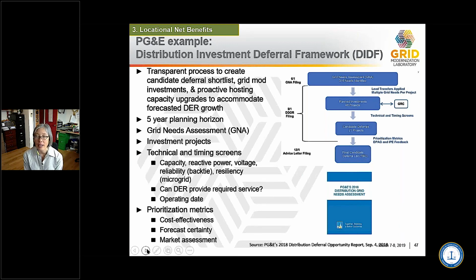So what does the process look like? You use some of these components that I talked about already. PG&E establishes a load and DER forecast and disaggregates that DER and load forecast down to each substation and each feeder. And then they do technical studies and ensure that the system can operate under normal and abnormal conditions. If there's a problem, like there's an overload on a specific circuit, they need to identify that need. When is that going to happen? Which hours does the problem occur?